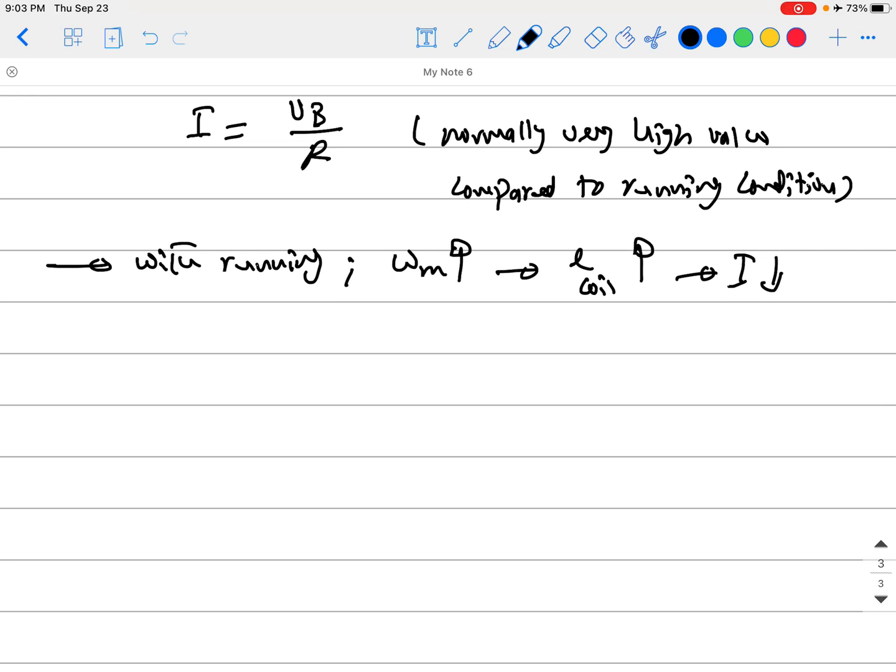So that's a very important hint about most kinds of machines you'll be dealing with: when the machine's starting, when you hit the start button, the machine draws a very high current. We call it the starting current or the inrush current. And just after the machine starts rotating, this current starts going down gradually until it goes to its regular running condition current. That's a very important thing. You'll see it with your own eyes in the lab, and in all the standard industrial facilities.